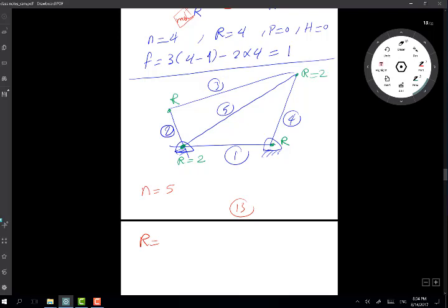The reason is I have three links connected in this junction, and three links connected in this junction here. Normally the number of joints at a junction is equal to the number of links minus 1. The way we think about it is we fix one of the links, as if it was a stationary link, and then the other links start moving with respect to that stationary link.